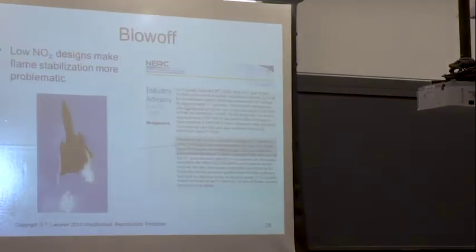So think about General Electric. These guys are awesome. They're incredible engineers. The modern, let's say a 787 engine, a GE90, is running, let's just say, at 1400 degrees Fahrenheit, 55 bar, running Jet A. You're blasting the fuel into the air, and that stuff really wants to auto-ignite. It really wants to ignite very quickly. So there's an enormous amount of engineering and design that goes in to not auto-ignite, because if it does, you get things like this.